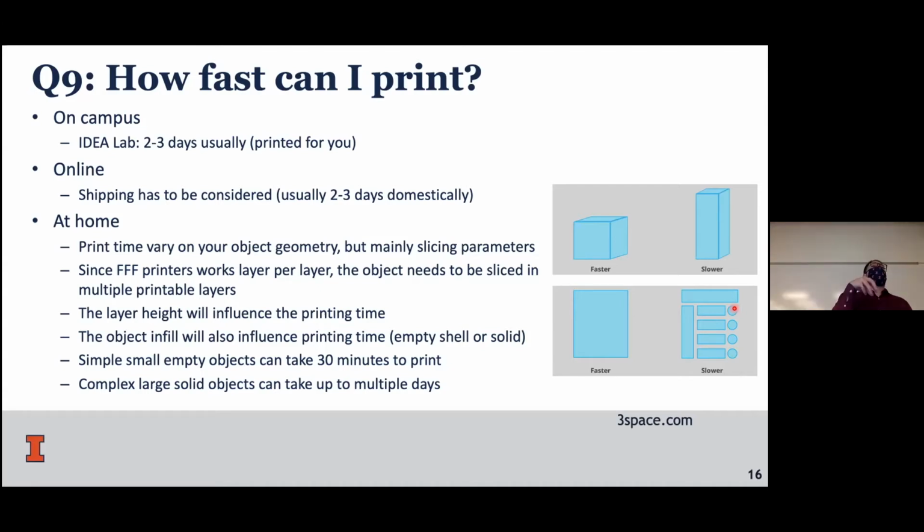So what I did is I installed a camera. These printers don't have cameras on them, but I installed a network camera so you can monitor and make sure there's no problem. For example, the filament was close to the end, and I thought, okay, everything's going good, there's 2 hours left to print, I won't monitor it, but that's where all the problems happened. So it's good to go check once in a while. Since it's heating, it's also safer to monitor for fire hazard. Problems that could occur are a jam of filament, running out of filament, a blockage of some sort, or a power outage. Any other questions?